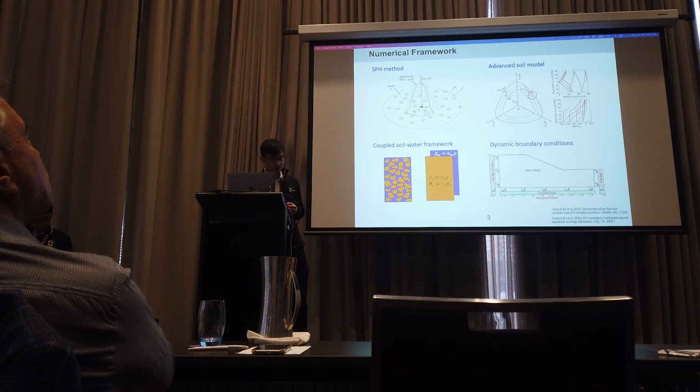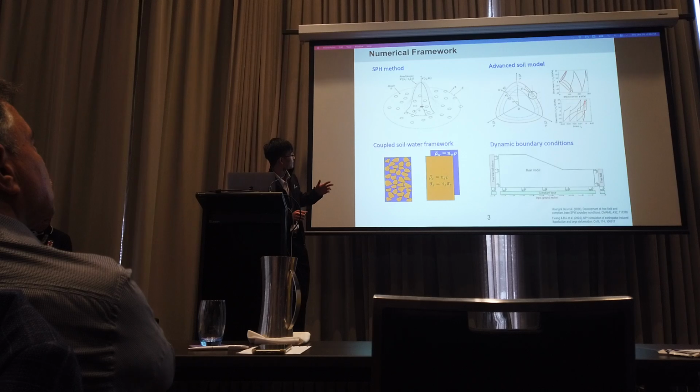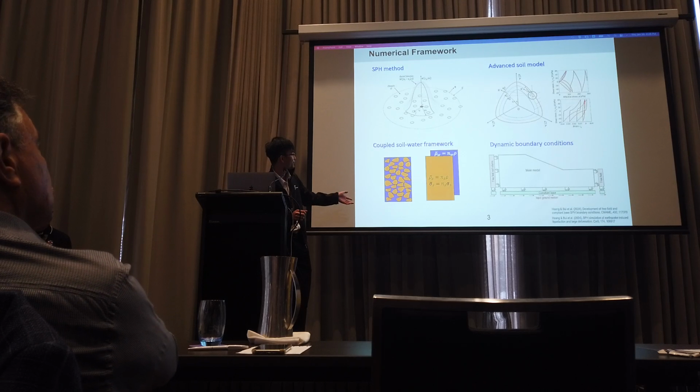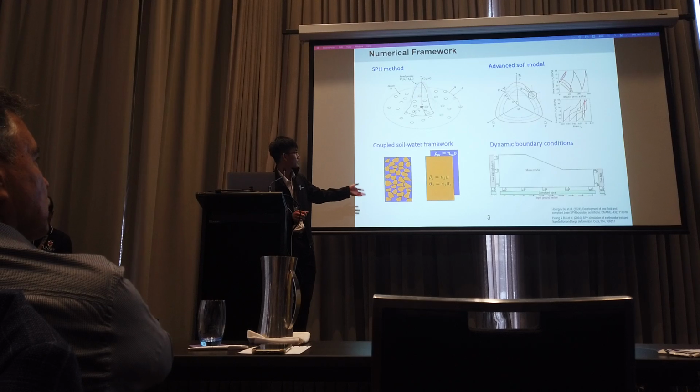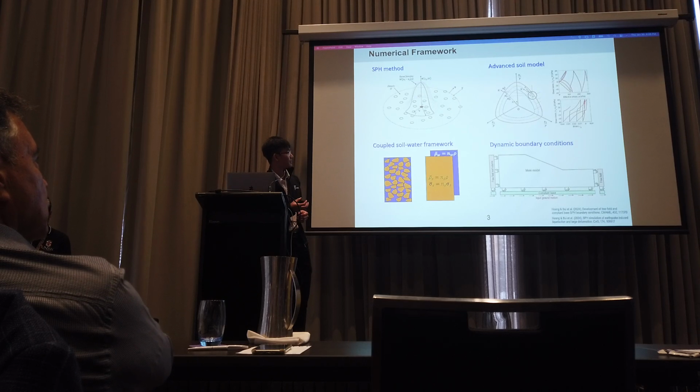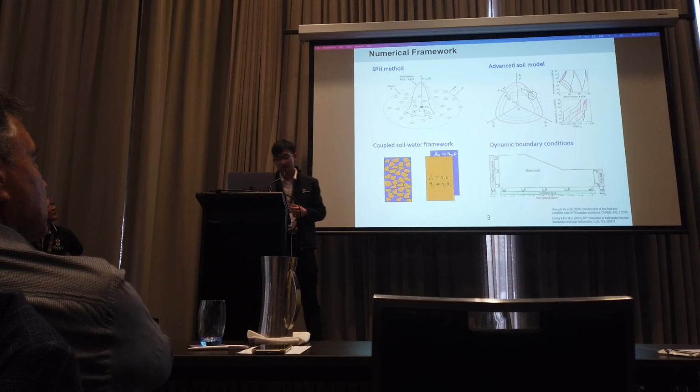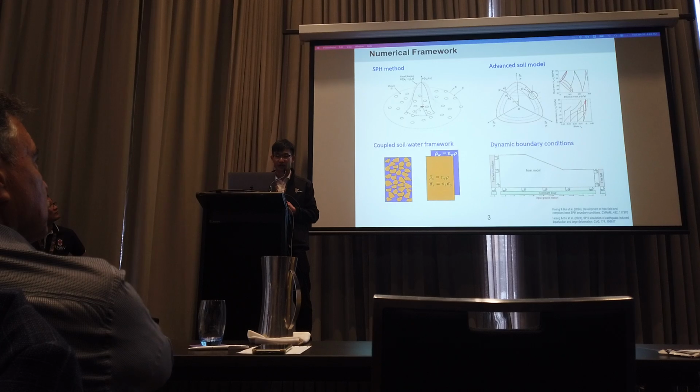So here is the general fully coupled SPH framework to analyze the coupling interaction between the pore water and the soil skeleton under rapid loading of the earthquake. And additionally, we use an advanced bounding surface plasticity model to capture the cyclic response of the soil under earthquake, including the liquefaction response, the degradation of the effective stress, and the buildup of excess pore water pressure.